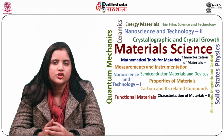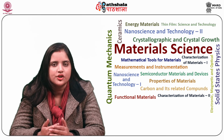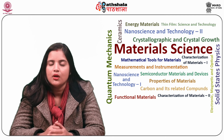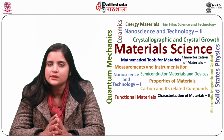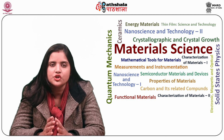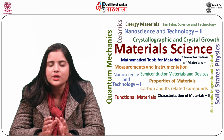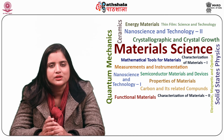Let us next study ion implantation. Ion implantation does not create an overall new layer, but it forms alloys with the substrate surface, thereby altering the chemical composition of the surface. For instance, nitrogen is employed to enhance the wear resistance in metals.